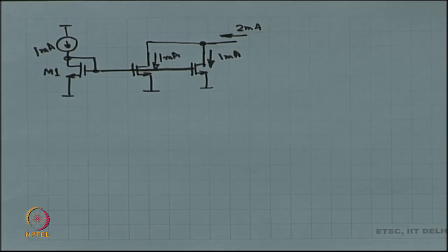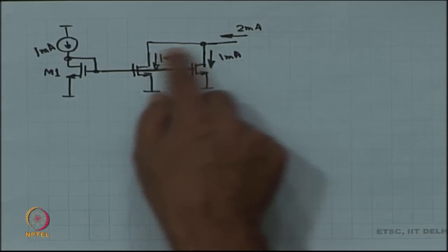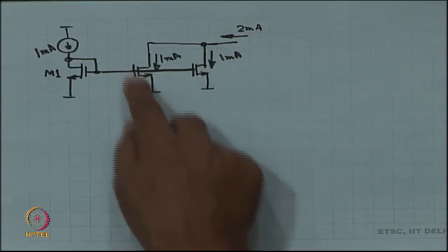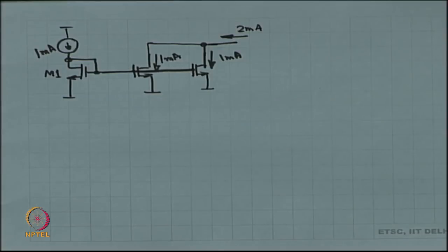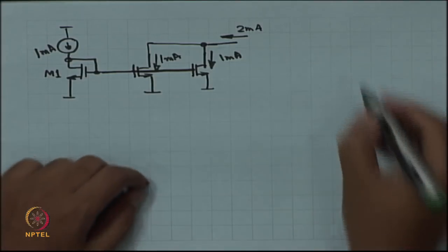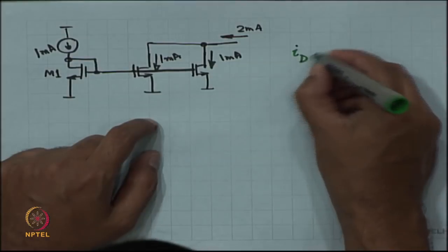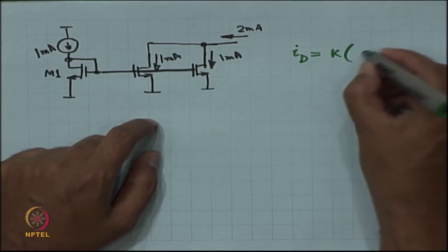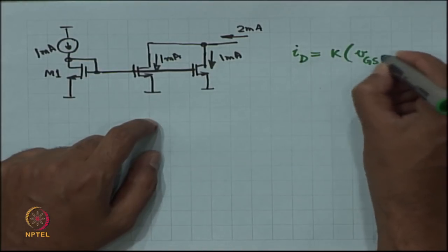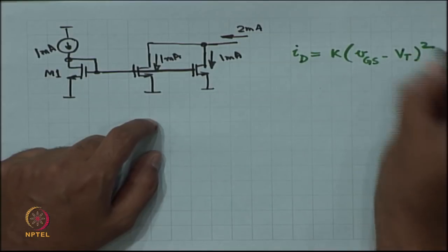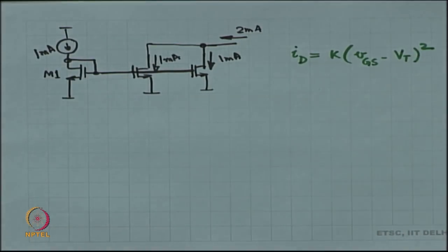Okay. So, the way we do this, actually at the end of the day you could implement it in this fashion, but we have some shortcuts. So, the MOS device equation that you studied, what we projected over here was I d equal to k times VGS minus VT the whole square, okay, where k is some constant.